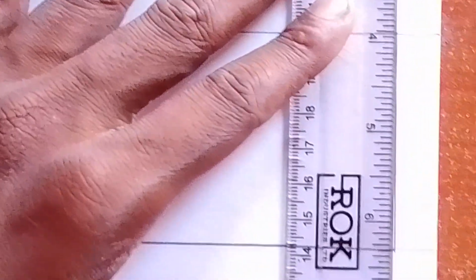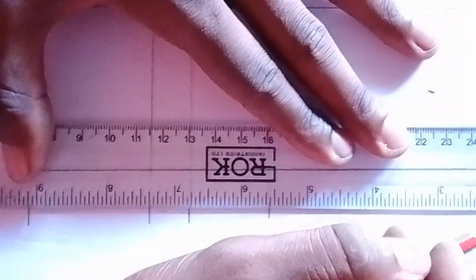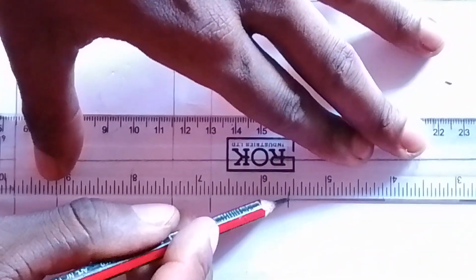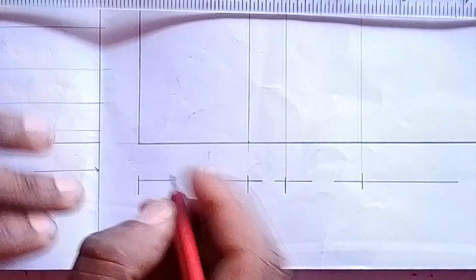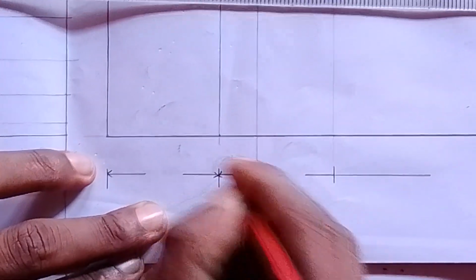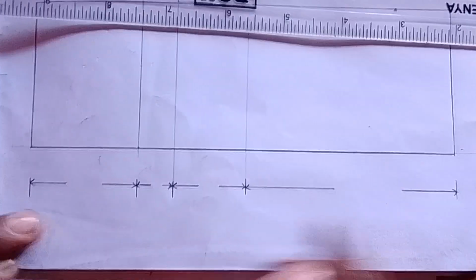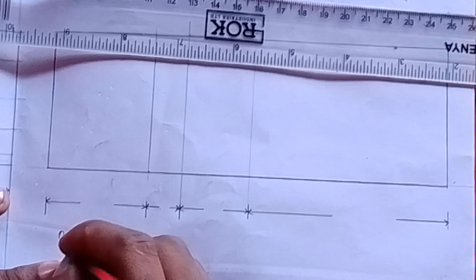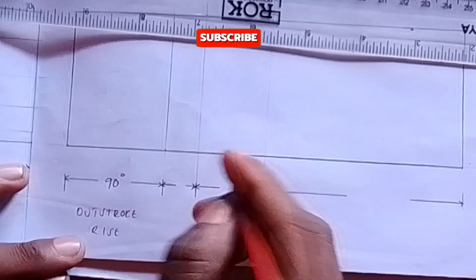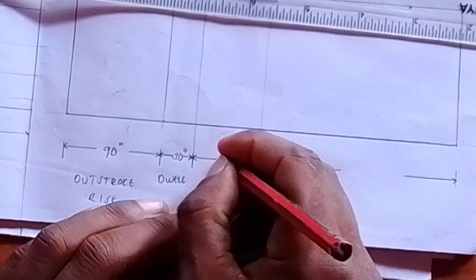Then the rest, we are told it is dwell. So the rest we don't have to measure, you just know the rest of it is 12. So you label your work very well so that your work can be presentable and the examiner can know that this person is on the right track. Here we have this, this, this, and this. This we have said is the outstroke or rise, and you have given it 90 degrees. This is the dwell, which you have given 30 degrees, and you have given this as 60 degrees.